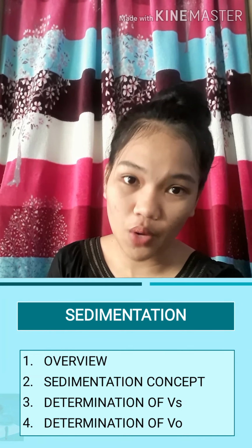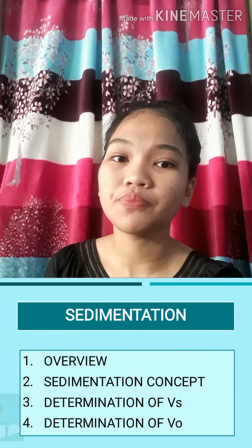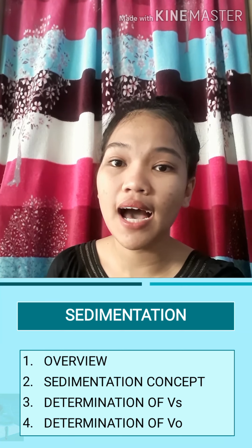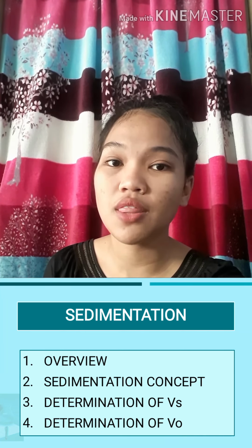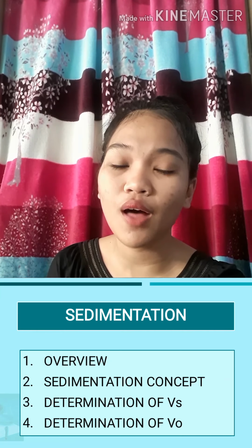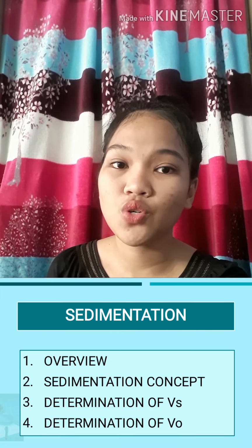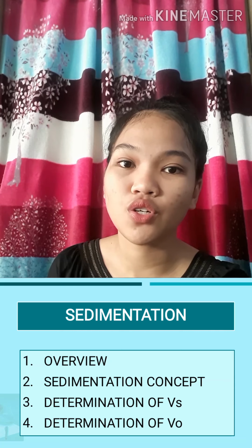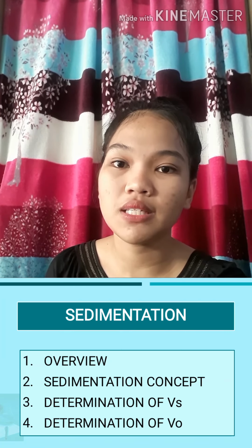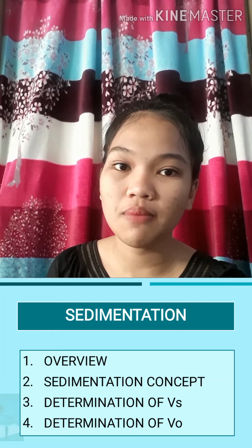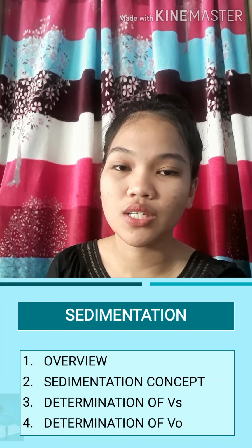For our type 3, or zone sedimentation, particles are at high concentration, greater than 1000 milligrams per liter, such that the particles tend to settle as a mass, and a distinct clear zone and sludge zone are present. Zone settling occurs in lime softening sedimentation, activated sludge sedimentation, and sludge thickeners.